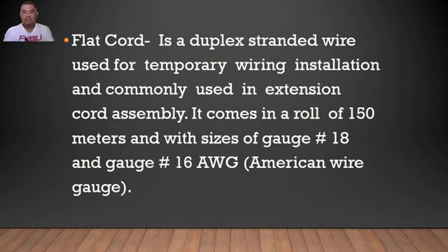So it comes in a roll of 150 meters and with the sizes of gauge number 18 and gauge number 16. So American wire gauge, no? So the flat cord is usually used for temporary wiring, meaning it is not used permanently. Sometimes the most common use of a flat cord is on extension wires. Okay,